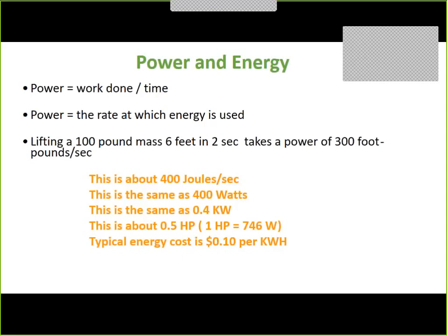And we typically pay for kilowatt hours, 10 cents a kilowatt hour. So it would cost you, if that 0.4 kilowatts is used for a whole hour, that would be 0.4 kilowatt hours, and that would cost only 4 cents.